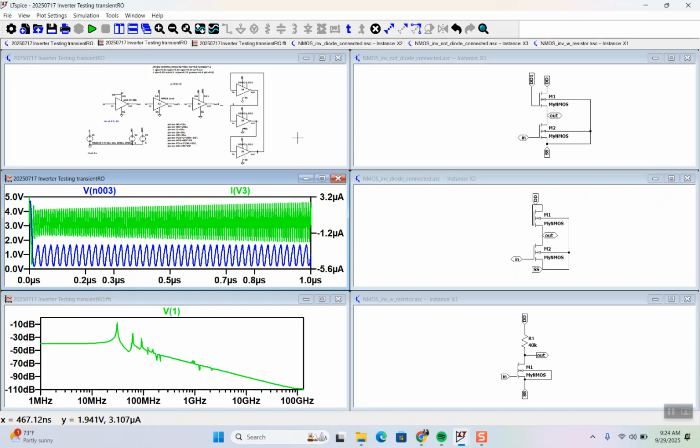They extract a spice deck, and the circuit designer just has to take it and then be clever with getting things to meet power and timing and logic level. Okay. But again, we're using NMOS loaded logic, not CMOS. It's an older technology, but it's a much easier thing to do research on various layers. Right? Anyway, that should be it.